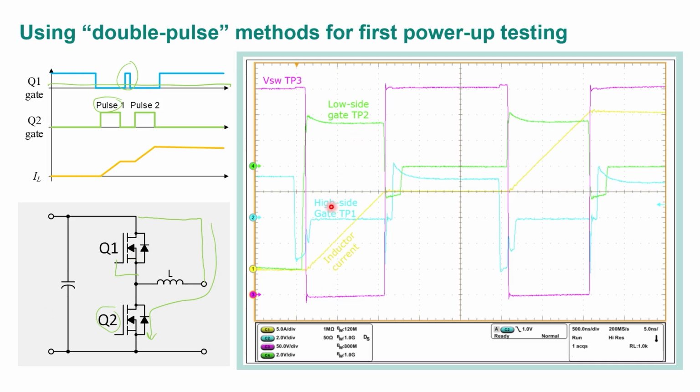So if I look at, for example, my low side gates, this would be Q2. Here is turning on, turning off. And then similarly, you can see the high side, a short dead time, high side turns on, high side turns off. This is the voltage. You would see then VDS, so that's the switch node voltage from right here. And you can see the inductor current is measured with a current probe here. This is at 5 amps per division, so 5, 10, so this is 15 amps, then on up to 30 amps. Everything looks good. There's nothing unexpected. That's what we're hoping to see.